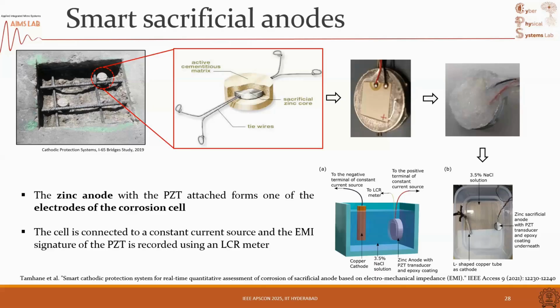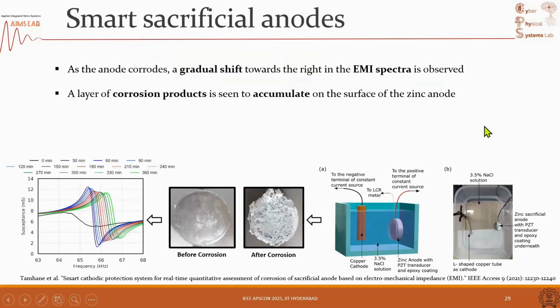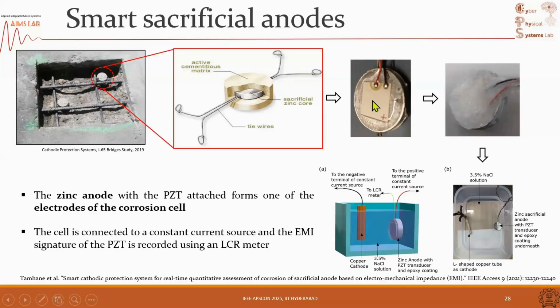So once you put in these anodes, you don't know how long they are going to last. So then you do some periodic replacement. Every 3 years, maybe you replace the anodes on a ship, etc. That's how it's done. So we thought we'll monitor this. Our sensing mechanism was to connect a piezoelectric transducer to the zinc anode. This is just a piezoelectric wafer transducer, the kind of thing which we use in our ultrasonic testing.